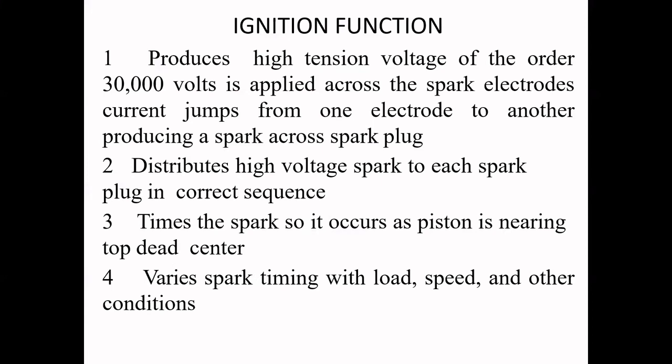The timing of the spark is very, very important. At what instant the spark should be produced is a very important parameter in the ignition system. The spark should be produced as the piston is nearing top dead center. During the compression process, the piston moves from bottom dead center to top dead center.